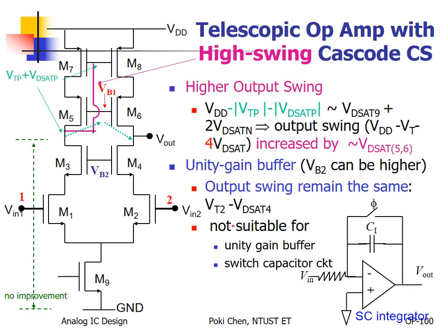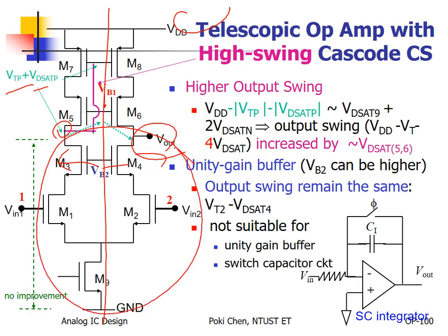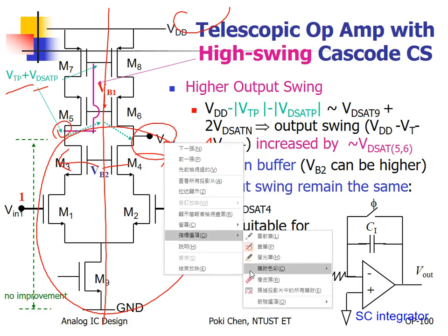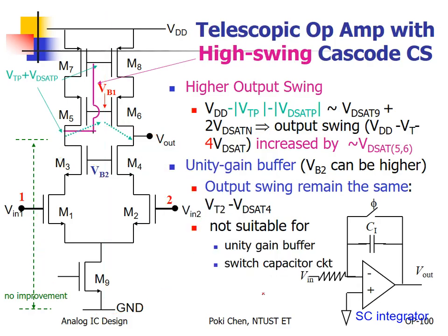Roughly speaking, because it is symmetrical, to the left, to the right, so how much voltage here? VDD minus 1 VT, 1 delta V, right? Similar for that. That's it. Okay, and that is for the maximum. But do you modify anything here? I mean, compare this new circuit.